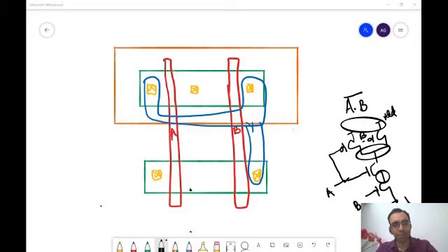Anything else, Devajit? Sir, in the middle one, in that contact to poly, there is contact to poly capacitance on both sides. So there would be some load capacitance also. So if we could make the parasitic capacitance less somehow, then switching could be done faster. Means we have to discharge and charge less. Okay. So what should we do?